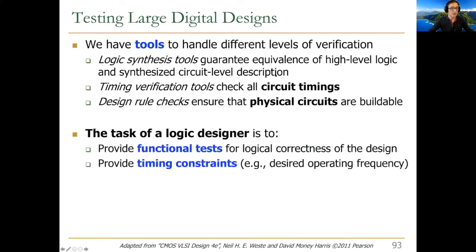But the task of a logic designer is to provide functional tests for logical correctness of the design and to provide timing constraints, for example, the desired operating frequency, to make sure that the design actually works, right? And also you need to somehow make sure that the hold time constraints are not violated, right? That's also the task of a logic designer, unfortunately, as we have seen earlier.